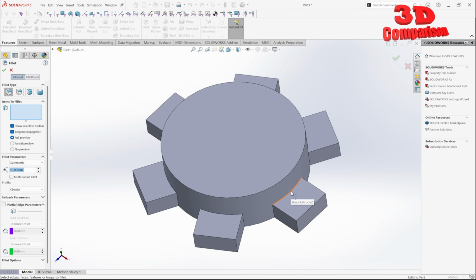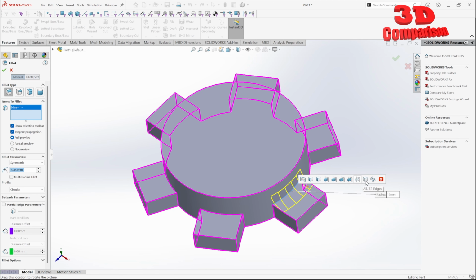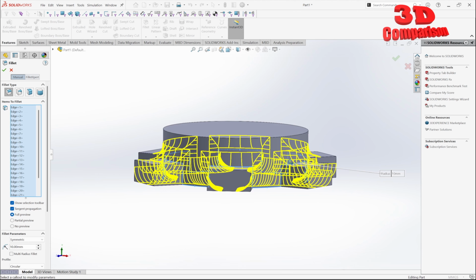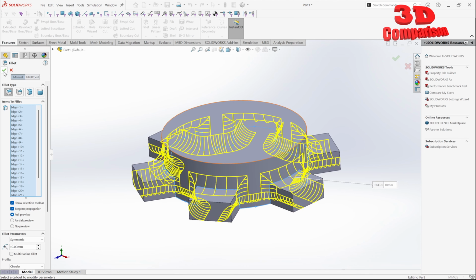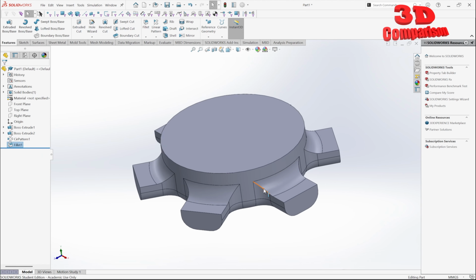But if I do it over here, where we have that merging between one extrude and the main cylinder, we're going to see that if I go with the following option, connected, right loop, in this case we have an additional one. It actually understands that maybe there's a loop over there. If I click apply, it will apply the following.